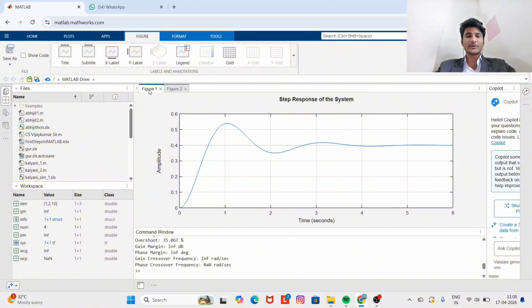using the frequency response. And from both analyses, we conclude that the system is stable, slightly underdamped, and has a moderate speed of response. Also, we observe that the time domain and frequency domain parameters are related, which helps in better understanding and designing control systems. So this was all about the conclusion on the outcome of the activity.